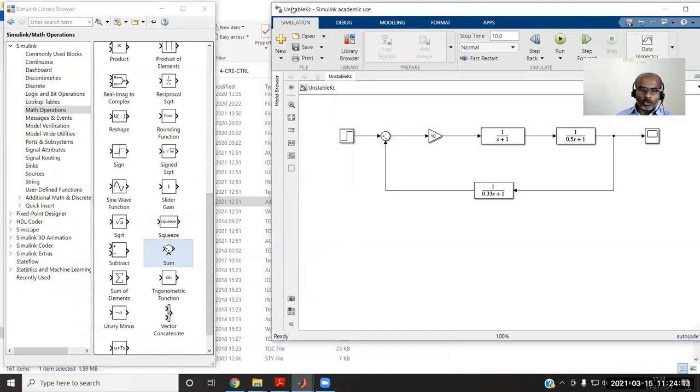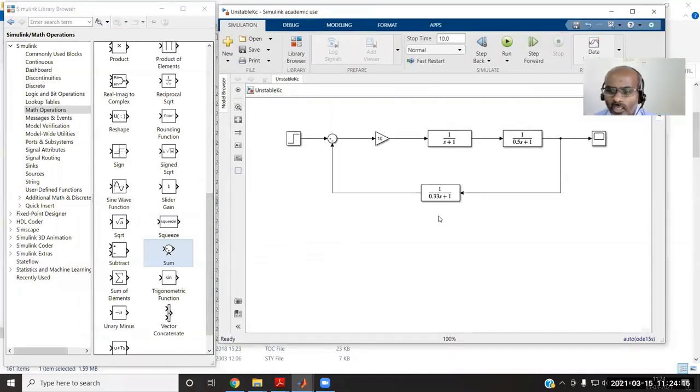Okay, we have a closed loop. The measurement is also having a transfer function, which means measurement is also having some lag, or is a first order system. For fast measurement, you can take it as simply a gain of 1, a zero order system. Gain is a zero order system, or proportional control is a zero order system.